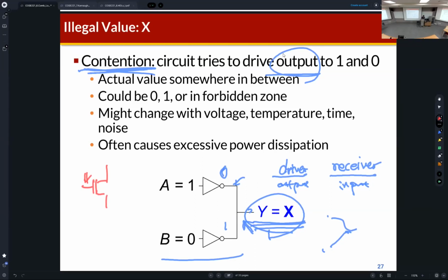So this is the NMOS transistor. One node of the NMOS transistor is connected to ground, and another node is connected to the output. So which means that using the current flowing from VDD to ground, the output signal of the digital circuit is driven.